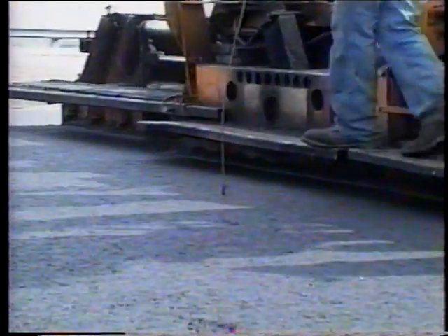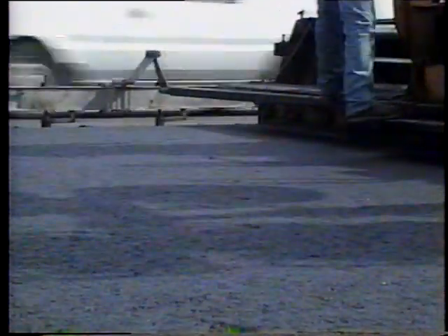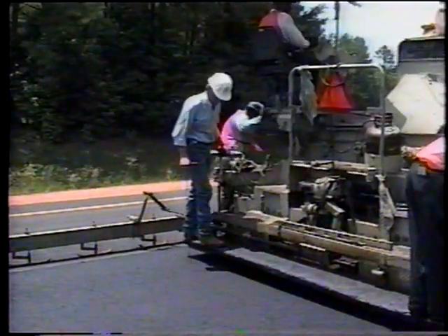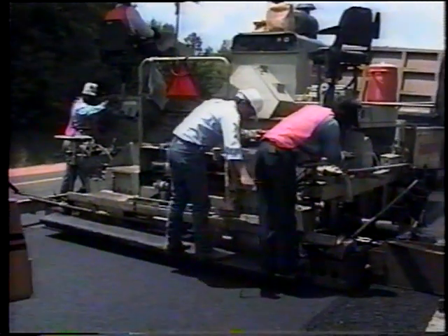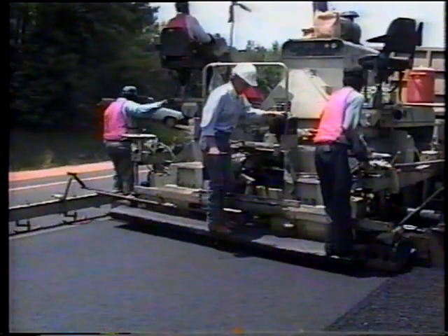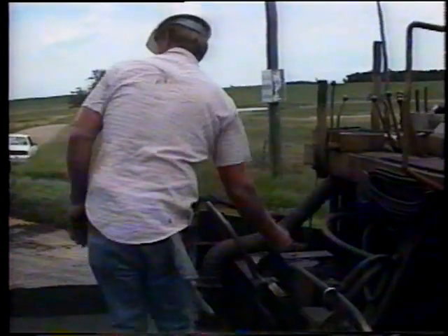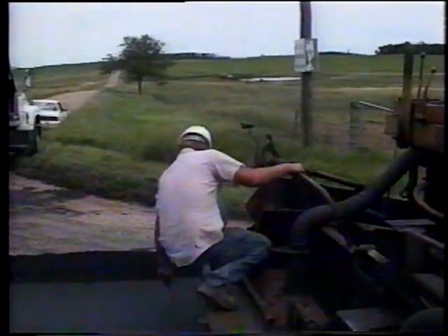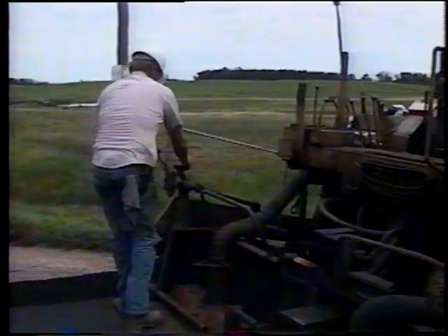The depth of placement is also important. The contractor should make several loose depth checks using a depth gauge. A general rule of thumb is that the mix will compact about 20% in depth. So as an example, if the course being placed is supposed to be 60 millimeters thick, the loose depth should be about 75 millimeters. If changes in depth are necessary, the contractor should make the adjustment gradually. Both you and the contractor should then let the paver advance about 10 meters before rechecking the depth and making further adjustments.